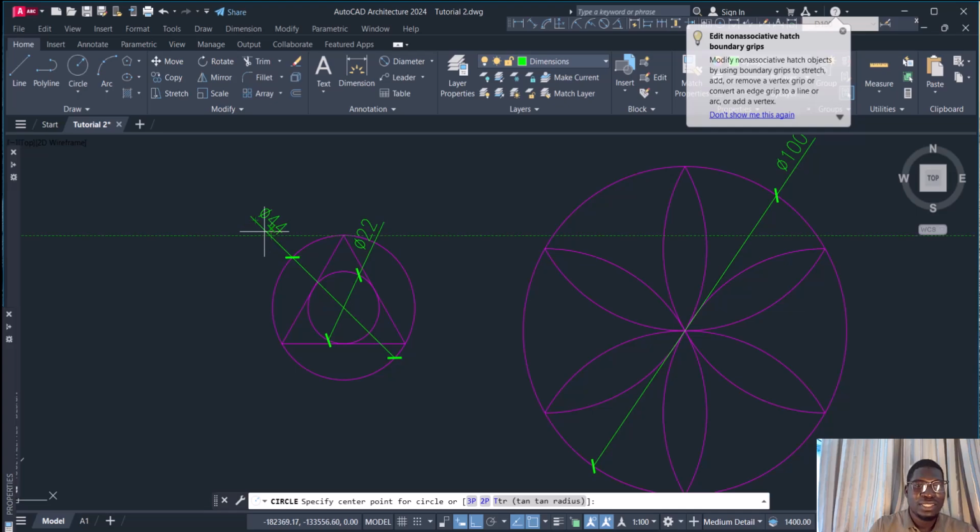The diameter of this circle, the bigger one, is 44, and then the other one that is inside is 22. But that one is not necessary. The important thing is the bigger one. So first, you can use C space or C enter as the shortcut for circle.